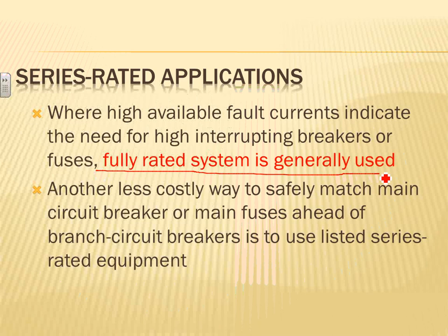Fully rated equipment. This is mainly used if you're feeding any rotating machines, any machines that can kick back short circuit. So if you have an air handling unit, rooftop unit, chillers, and so forth, your system has to be fully rated. And a good example of this is the main panels in a bigger building, as well as mechanical panels, owner equipment panels if you have a manufacturing floor, and so forth.